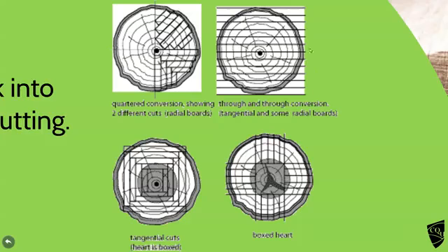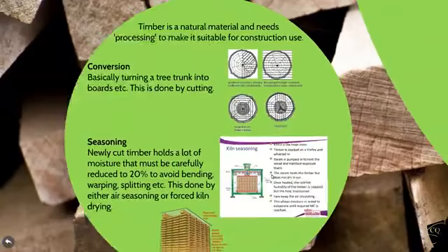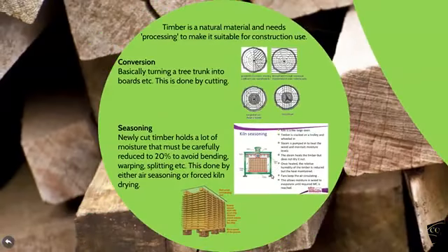That one's just cut straight across, that's quite good, but because you're going across the grain, that can lead to defects later on, which is why we end up having to dry the timber. You can box cut, tangential cutting, or the back, so you can cut round and avoid using the very hard bit if you wish to. So conversion is basically cutting it up.